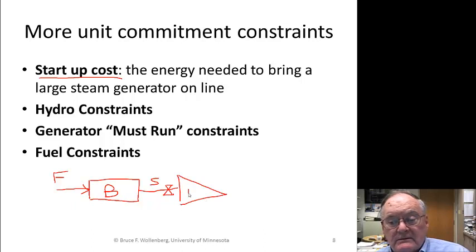And the turbine takes quite a while to start up, and we don't want to just blast all the steam in. We want to start running it gradually and let the turbine come up to speed and up to temperature inside, the temperatures of the blades and so forth. There's very critical paths that it has to follow, and eventually it starts turning the shaft, and we have a generator out here.